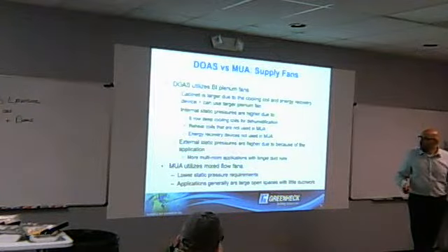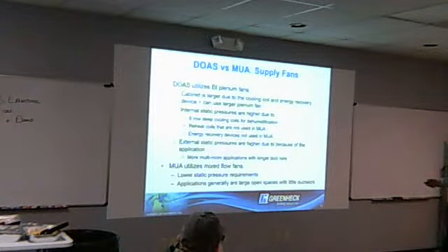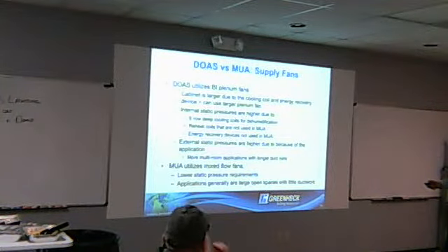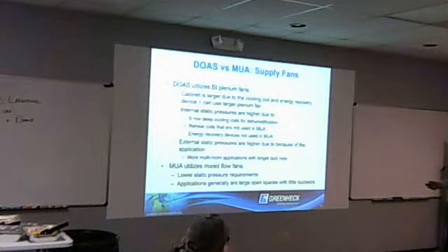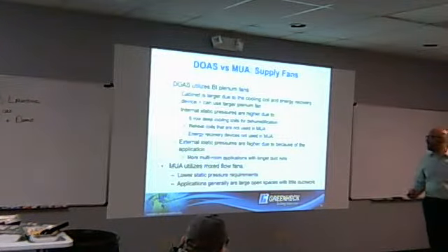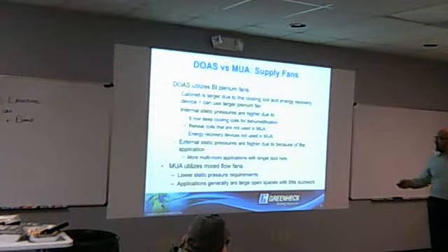Backward inclined plenum fans are commonly used because of the cooling coil or the reheat coil. The cabinets are usually a bit bigger, and we have deeper row coils and reheat coils that are not typically used in makeup air. So modulated hot gas reheat coils are not in makeup air. Energy recovery is usually not in makeup air. Most of these things we already talked about.